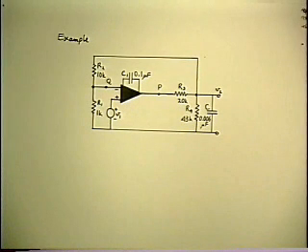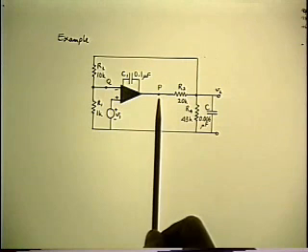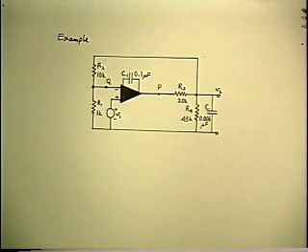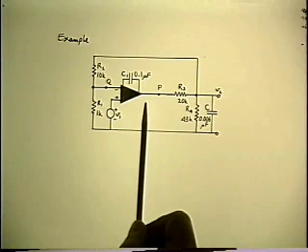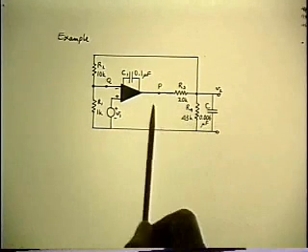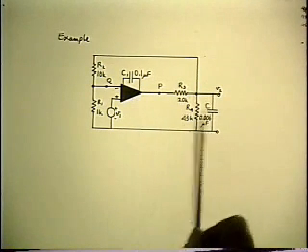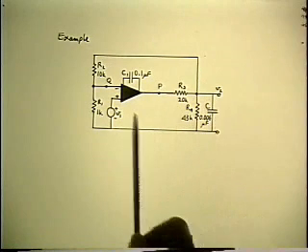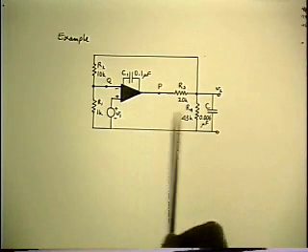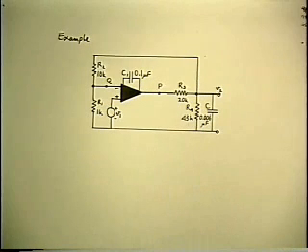I said earlier on, in justifying the selection of this operating point, I said the data sheet says the output impedance is very low, a few hundred ohms. I neglected to say the data sheet gives it at only one frequency. So maybe that's the culprit. So what I did was I made an independent measurement of the output impedance of the op-amp. And I can calculate the Z1 looking in the other direction. So using my measurements of Z2, dividing them by Z1, I can actually predict what the ratio Z2 over Z1 is.